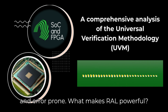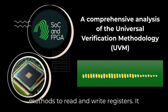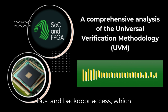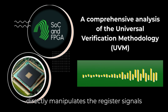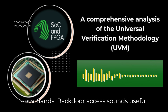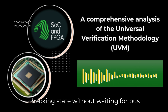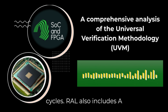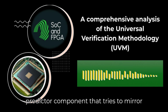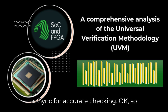What makes RAL powerful? Several things. It provides standardized methods to read and write registers. It supports both front door access, generating real transactions on the DUT bus, and backdoor access, which directly manipulates the register signals in the RTL simulation using simulator commands. Backdoor access sounds useful for setup or checking quickly. Very useful for initialization or quickly checking state without waiting for bus cycles. RAL also includes a built-in checking mechanism and a predictor component that tries to mirror the DUT's register values based on observed bus traffic, so your model stays in sync for accurate checking.